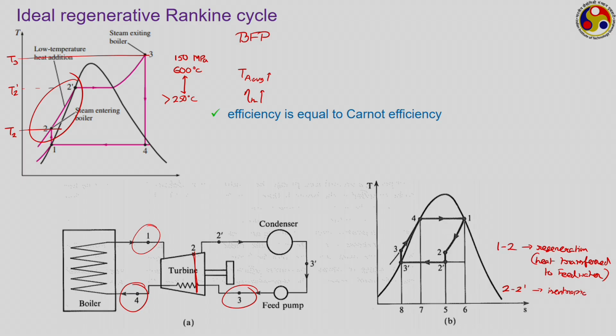As it is getting expanded, had it been an isentropic expansion something like this, of course, during the expansion it starts with a saturated vapor, but gradually it gets converted to a mixture, and during the regeneration part again it is getting converted to mixture, but the quality is decreasing very rapidly, and so the turbine towards the later stage, towards somewhere here, has to deal with very wet steam, which is always very much problematic. There will be a significant amount of erosion which can't be sustained in practical operation.